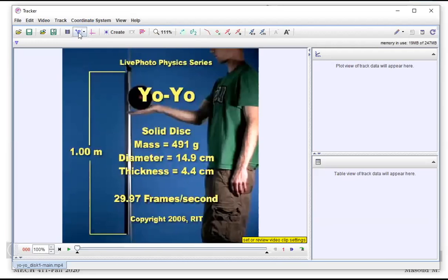So first thing, you go to this icon to create a calibration stick. I go to new calibration stick. Click on that, and pay attention to guidelines provided by the software. Here in yellow, it says shift and click to mark end one. So hold down the shift key. Once you do that, you see the mouse pointer changes.